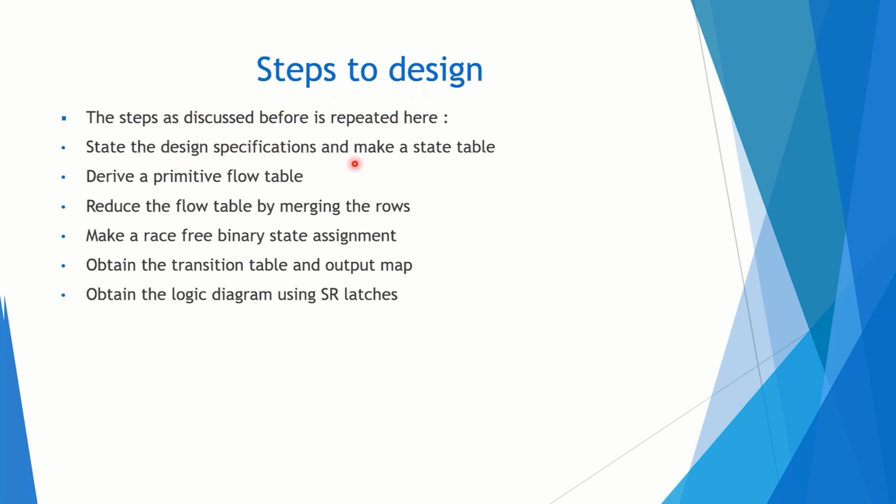State the design specification and make a state table. Derive a primitive flow table. Reduce the flow table by merging the rows. Then make a race-free binary state assignment. Obtain the transition table and output map, and then obtain the logic diagram using SR latches.